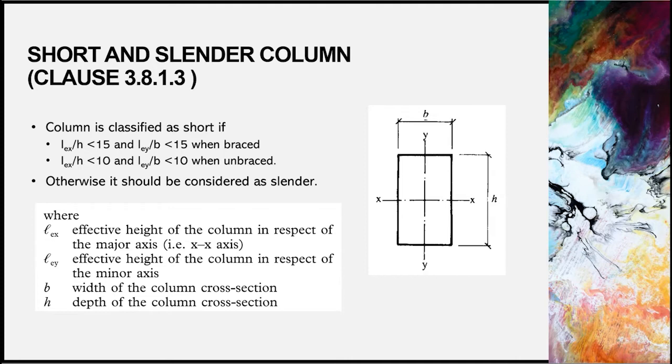No. Effective length is the length multiplied by a factor because you want to know what will happen to the column when you put a load on it. So it means the length that will buckle, the length that is affected for buckling. That is what it means. Okay, so that is effective length.